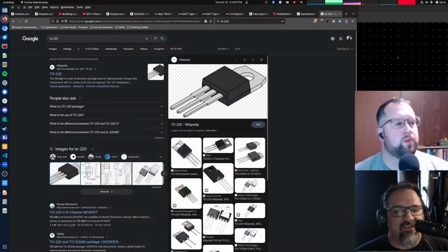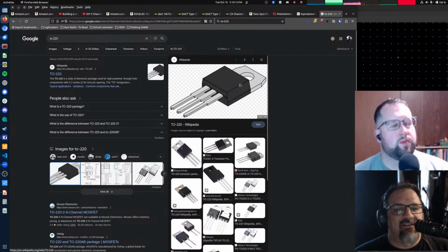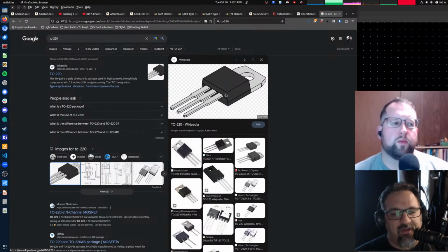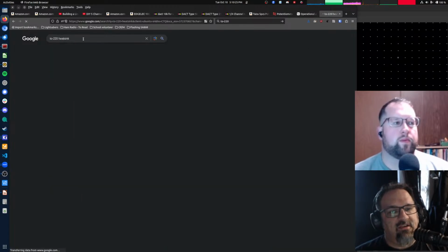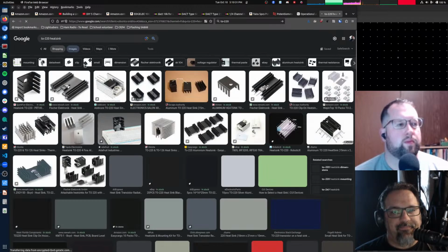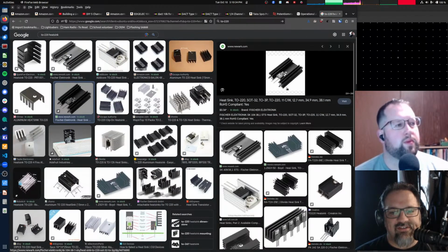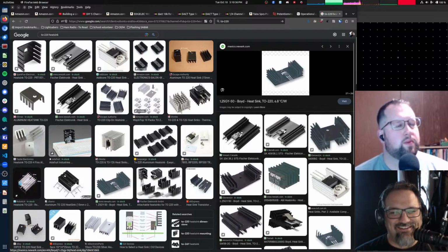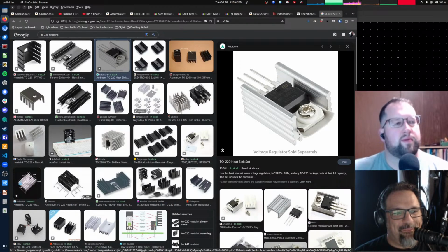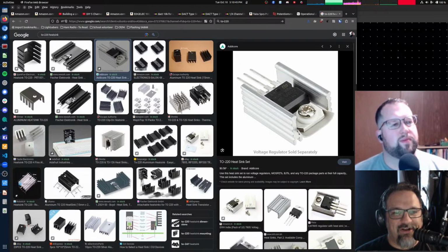I mean, you've seen these everywhere. This is a very common transistor package. It's called a TO220. TO stands for transistor outline. This happens to be the 220th transistor outline that they created. I don't know where that number actually comes from, but that's what a TO220 looks like. And then if you heat sink, they come in all shapes and sizes. Like really big ones, or little tiny ones, depending on how much heat you need to be able to dissipate. And on some applications, you don't even need to put heat sinks on them at all. The metal tab on the device will just be enough.